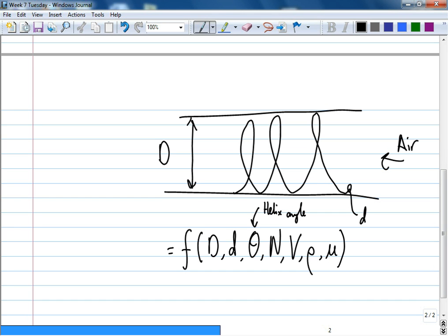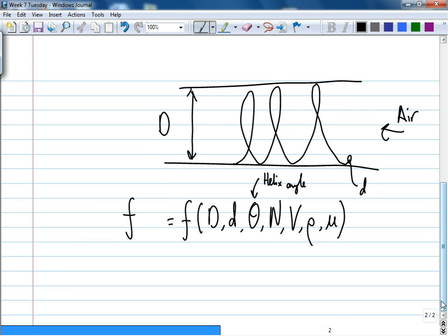The flow will go around this one and cause turbulence and cause some vibration. So we worry about the frequency, say. We make sure the frequency of the excited flow does not match any frequency of the structure that's holding the pipe, or the pipe or structure may break. So this one, don't call it F. Call it maybe G, some function, doesn't matter. Call it phi.